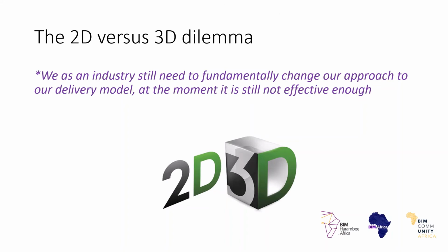That would help significantly with the change management process that we're experiencing on projects at the moment, because it is a lot of work if you do a 3D model and produce your 2D drawings and then there's a change. You're having to change the 3D model and then update the drawings. Yes, you're working in a BIM environment, so yes, the 2D does update, but there's still annotations and that sort of stuff that you need to go and change, and that's really not an optimal approach to getting the biggest benefits out of a BIM process.